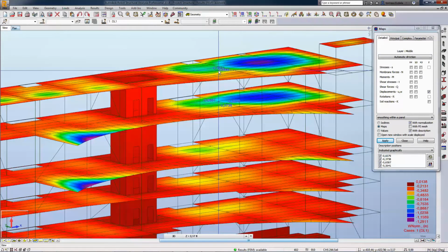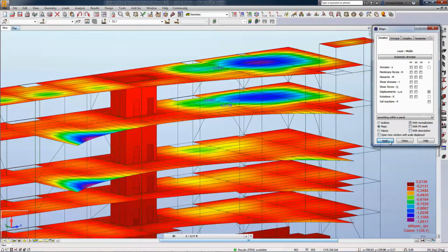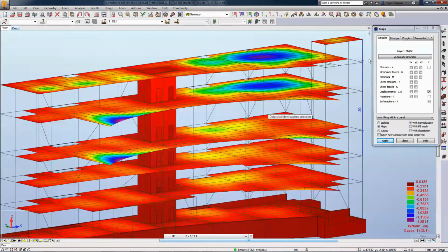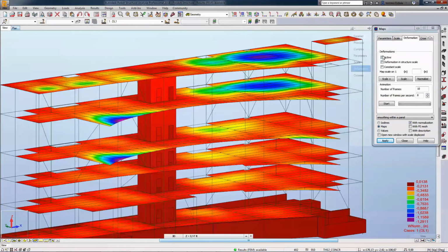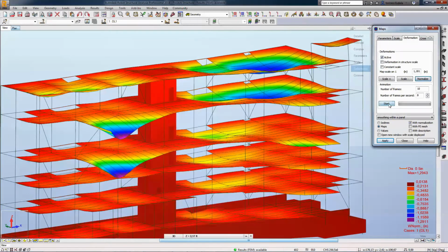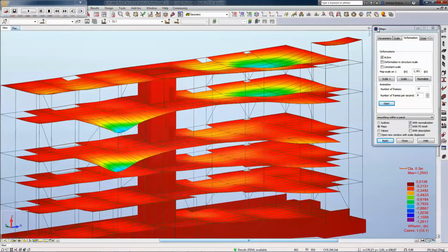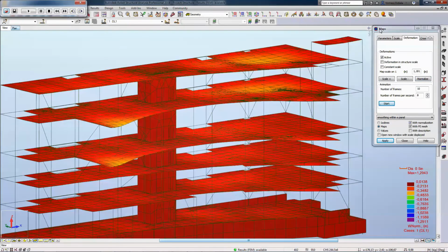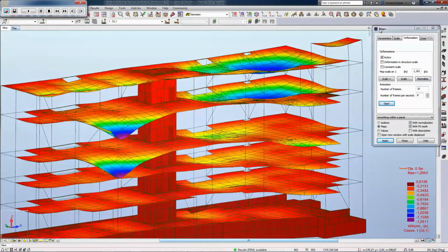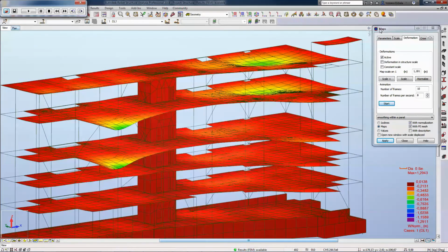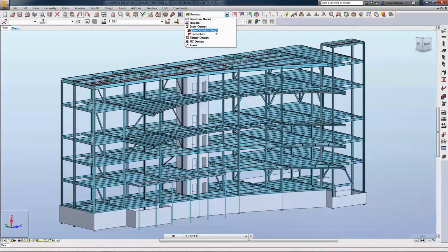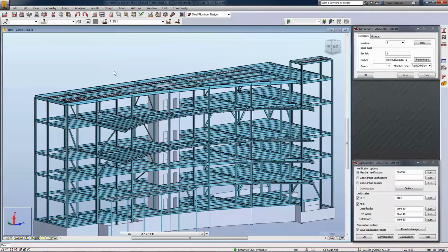What we're doing there, we're hovering on the different beams, and we're able to actually see the results for specific components in our structural model. The map I'll show you now is a deformation map, and we're able to also animate and show the deformation of our structural analysis as well. This can be saved and exported out as a video file as well. I've seen working with architects in some cases, they wouldn't understand when we communicate deformation to them.